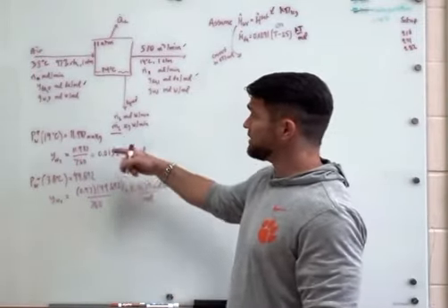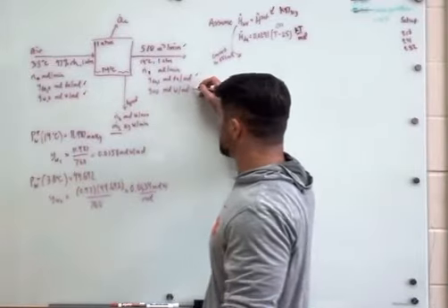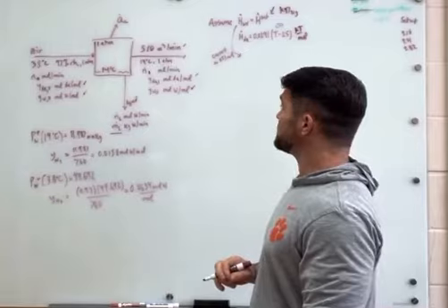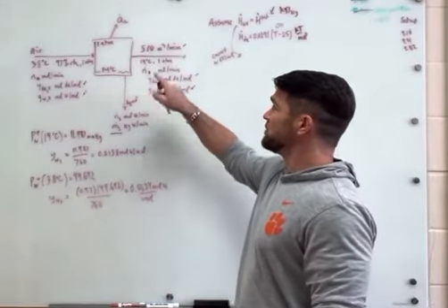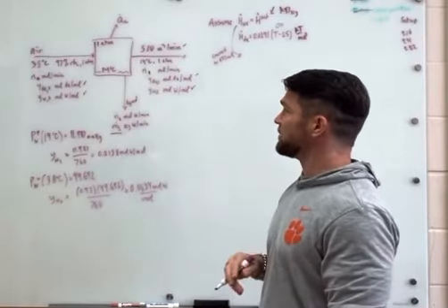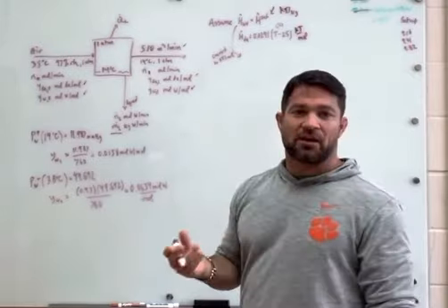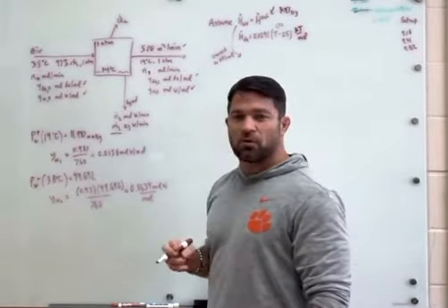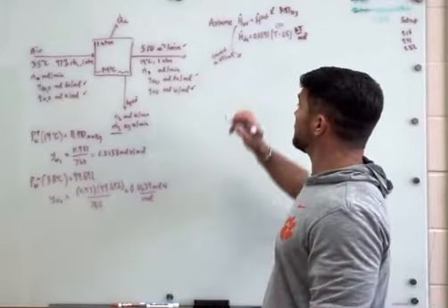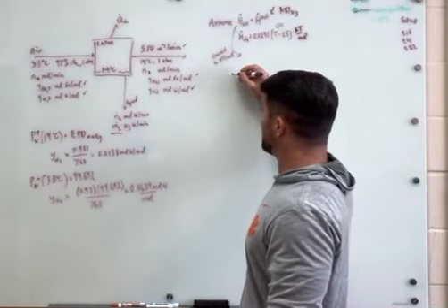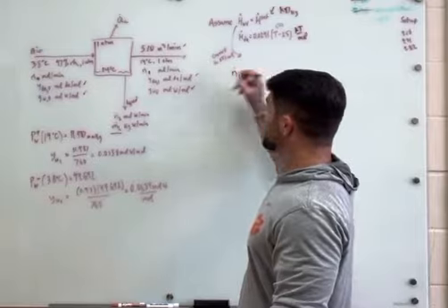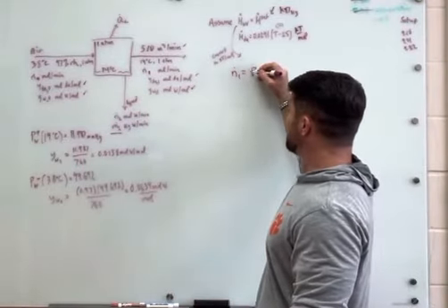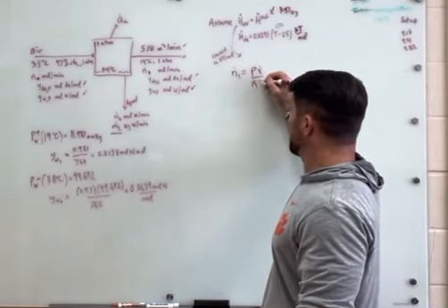Now that I know these, I also know the rest, because the mole fractions sum to 1. Now I can use the ideal gas law to determine the number of moles in this stream. Because it's air at low pressure and normal temperature, it's very likely to behave as an ideal gas. So PV equals nRT, so n equals PV over RT.